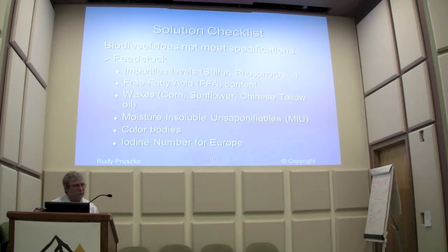Would a bleaching method take those color bodies out? Like with clay bleaching? Well, it might take some out. Activated carbon might help a little. Sometimes they distill the biodiesel, and that's how you get it water white. That actually seems pretty common from what I've heard.